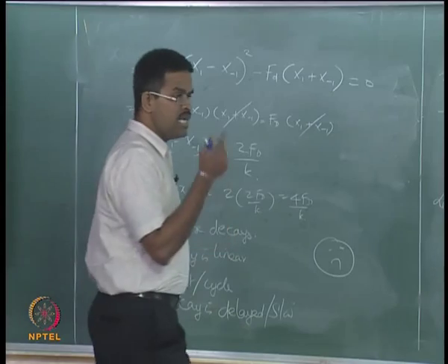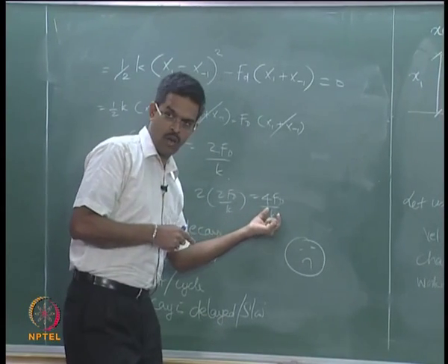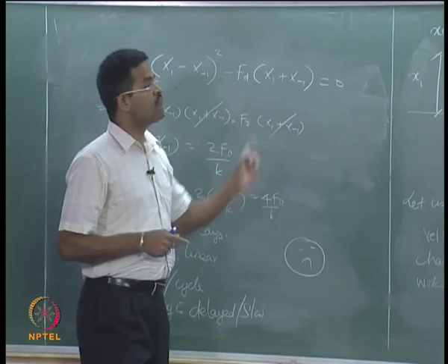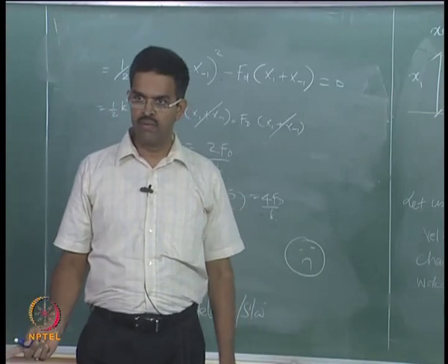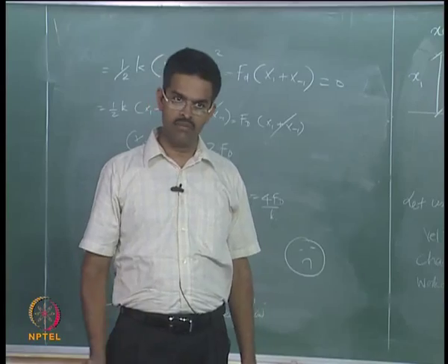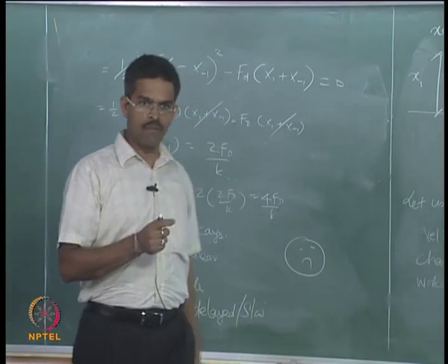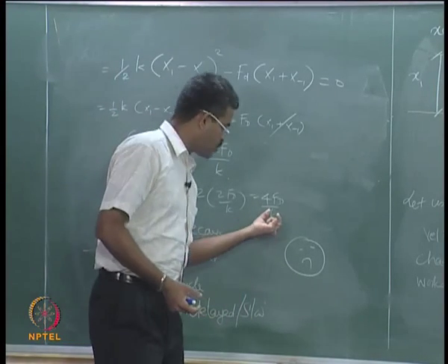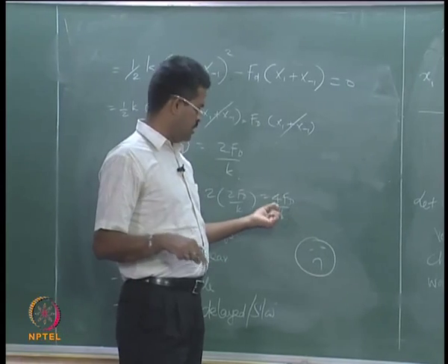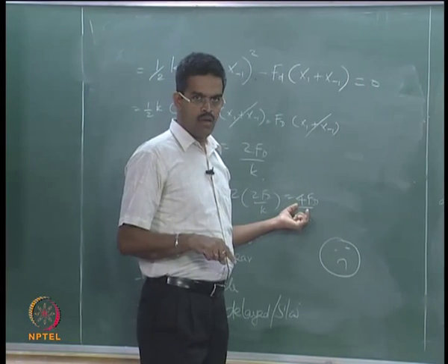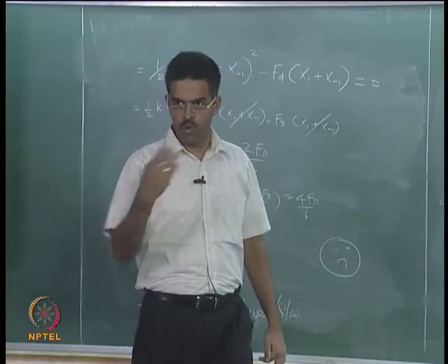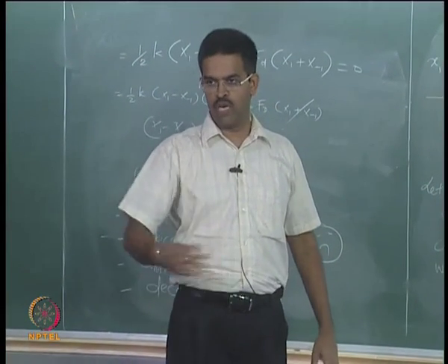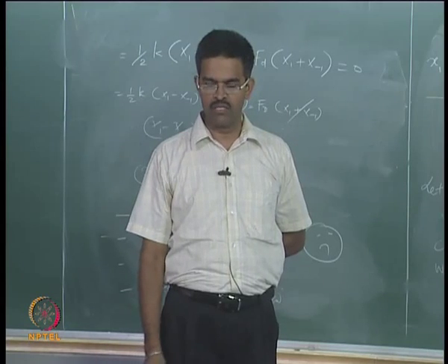Therefore, any damage caused to the elastic component in your structure will affect the damping cycle directly. That is another demerit in this model. Any damage you have caused to the elastic restoring component in your system, or the stiffness weakness or degradation of stiffness in your structure because of some loading phenomena which will happen, I will show you later in the next module of lectures.